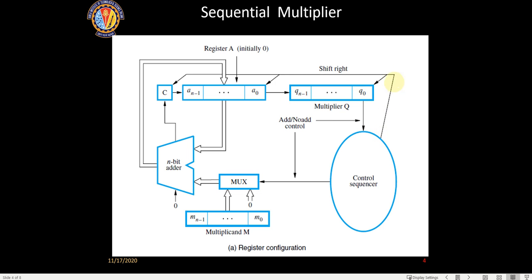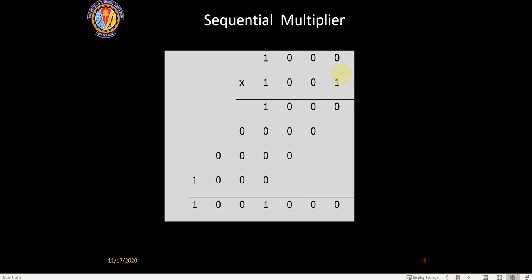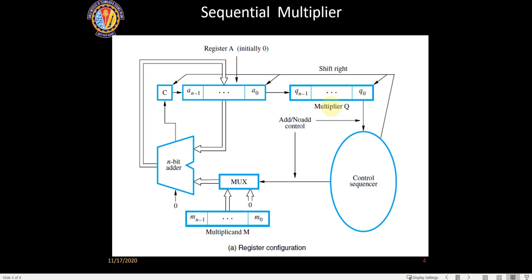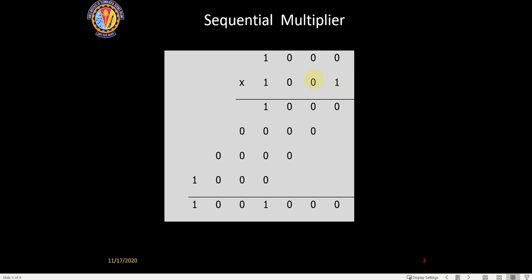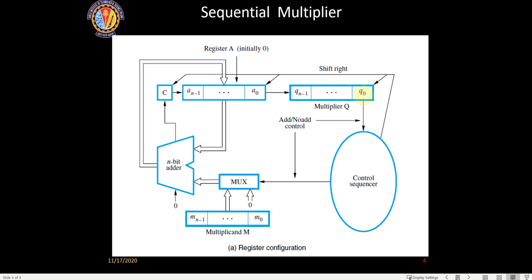So you have a control signal. Once the addition is over, say we are doing the load in the positive edge, in the negative edge what we need to do is shift it to the right. So the entire data will get shifted to the right. Whatever data was available here has shifted to here. Once we have used this data, it has become irrelevant, so we throw it out from here and push this data here. The next bit which is available here comes here.